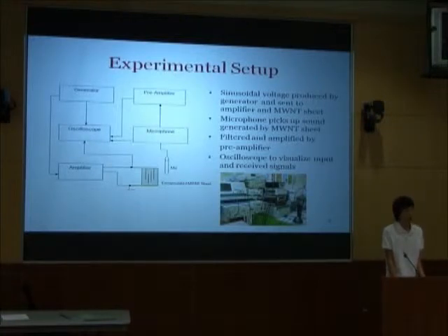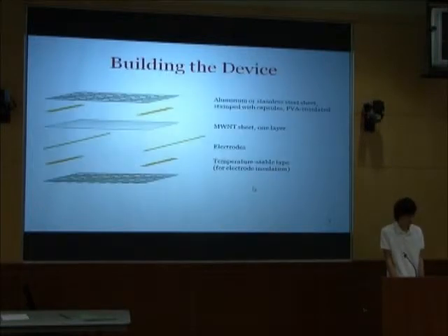You can choose low pass and high pass filters in the preamplifier to clarify the signal, and then all of this is sent to the oscilloscope where we can visualize the input and received signals. And we measured the peak-to-peak voltage of the received signal in millivolts.